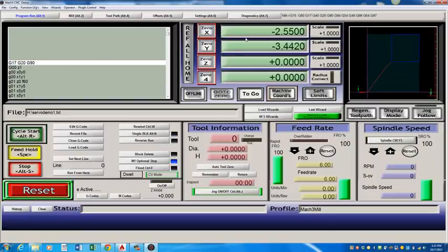So what I'm going to do, you notice we have X position, Y position. Your software will often open up like this. And in my next video I'll show you how to jog the machine and run it to a 0 point or an origin on our machine. Then you just simply click, I'm sorry, I have to push reset, 0x, 0y, 0z.